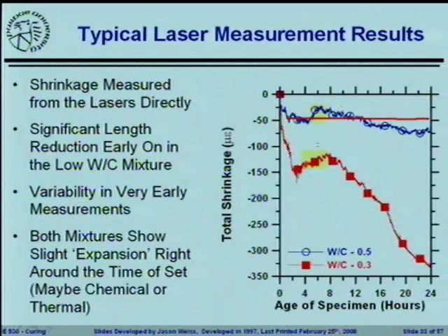All right. When you get to a lower water to cement ratio, you can see that the concrete's going to set somewhere around in this yellow box. Once the concrete undergoes final set, it's going to suck that water back in from the top surface. That bleed water that was up on the surface is going to be sucked back into the system, and the concrete is going to start shrinking dramatically. And you may have something that's 200, 300, 500, 1,000 microstrain taking place during the first 24 hours. That's a big deal, and that can lead to cracking.